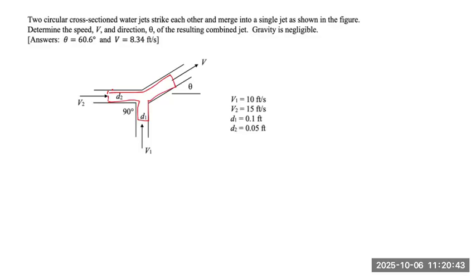And yes, we want to apply the conservation of mass equation again, which is d/dt of the integral over the control volume of rho dV, plus the integral over the control surface of rho u relative dot dA, and it's equal to 0.